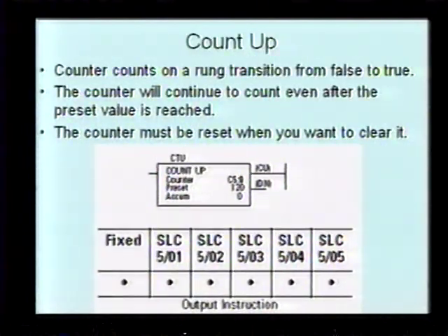The count up counter counts on a rung transition from false to true. The counter will continue to count even after the preset value is reached. The counter must be reset when you want to clear it.